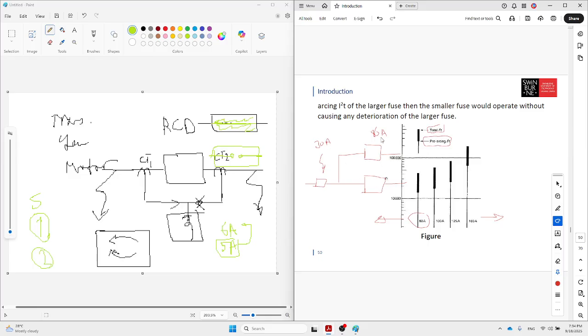Or to be better, I want to show you something. I change it to 80 amp. So how can we choose the backup for here? Choosing the backup is very, very important. If we choose 80, the nominal current that can be carried by this line is 80 amp, correct? Then for the backup, which is here, we cannot choose 100 amp. Assume this one carries only 10 amp. The total current here is 90 amp, okay? The total current here is 90 amp.